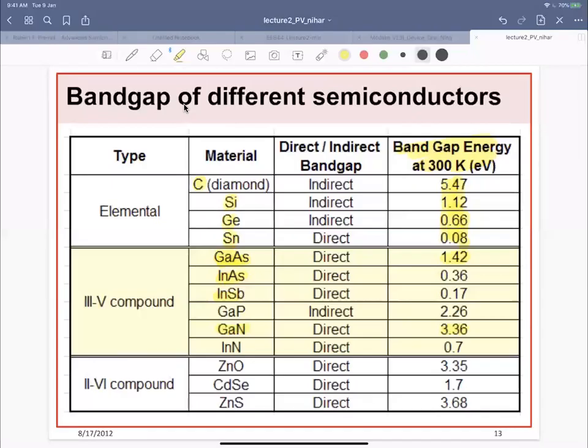So if you take the unit cell with the atoms and give it to a simulator, like the ab initio simulators such as DFT, it will give you the E-k diagram, the energy-momentum diagram, which gives you the bands. From the energy-momentum diagram, you can find out the band gap. The DFT, the density functional theory or ab initio simulation, is all done at absolute zero temperature.